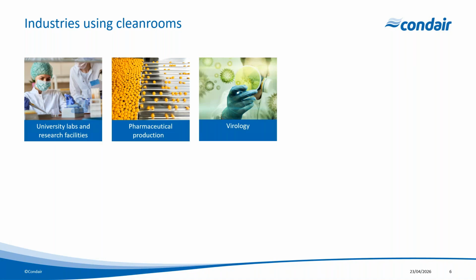And biology is also an issue. We may want to make sure that any bacteria is controlled by maintaining optimum relative humidity within a space. And also, if we're producing samples or growing cultures in a lab, then the environment can be critical to how those cultures will act and how they'll develop. So again, we specify relative humidity. Typically, that will actually be specified by the biologist.